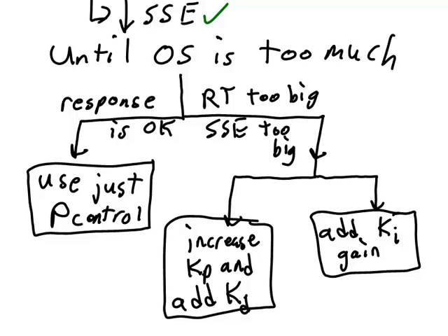For our robot joints, the kind of response that we want is very much the same as any other motion control application. We need our joints to be accurate, in other words, have low steady state error, we need them to be very stable, that is, have low overshoot, and we also want our joints to have a fast response, that is, have a low rise time.